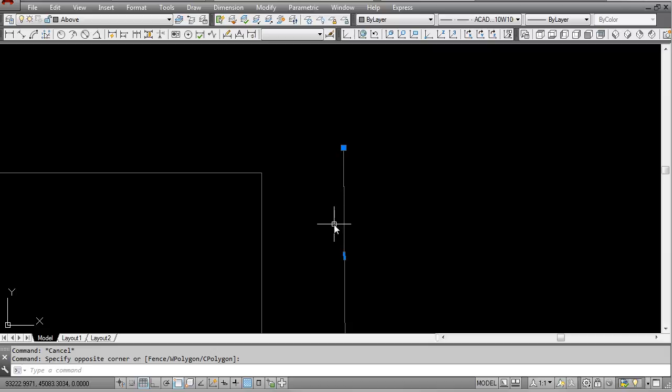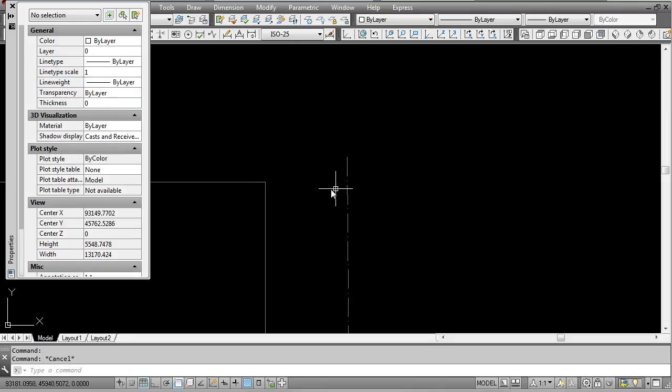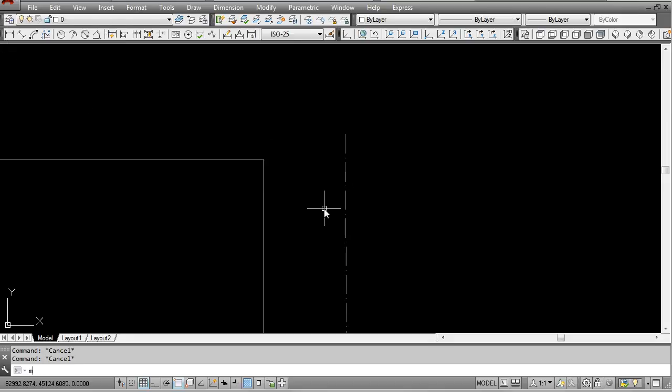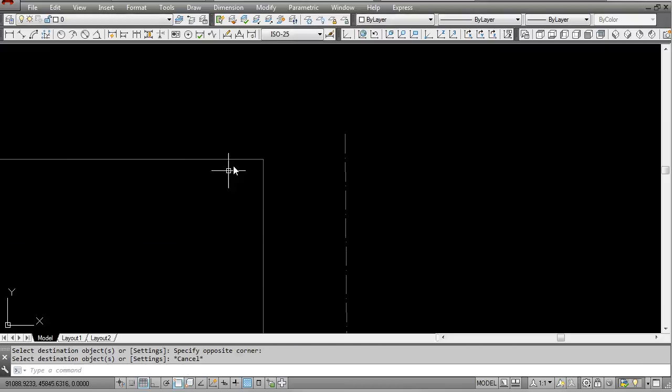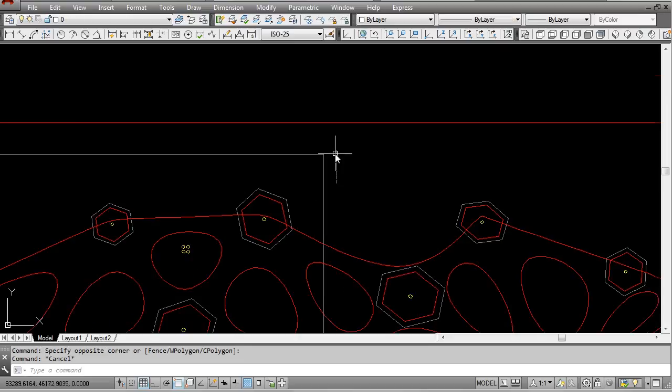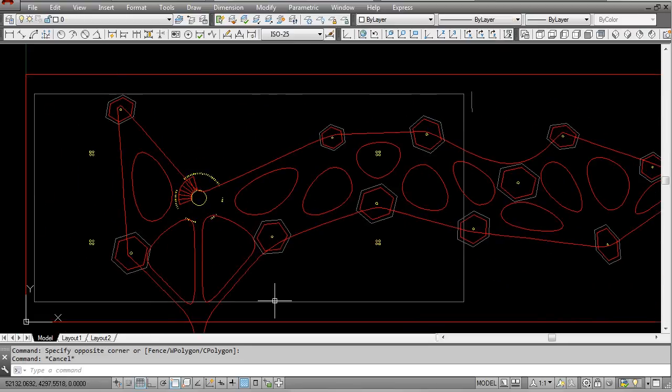To change the scale quickly, let me type Control-1 on the keyboard. I'm going to quickly go through these sizes and scale it up to a factor of, let's say, 30 so that we can clearly see it. You'll see that even though I match properties by typing MA between the two, this one is never going to show me the correct line type. The way we're going to get around that is by using a very small command that we're going to talk about in the next lesson.